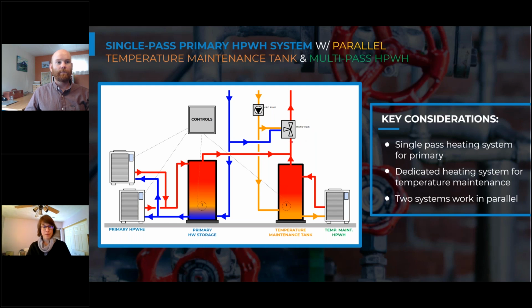Yeah, so this is a common way to pipe a mixing valve regardless of whether it's a heat pump or a gas water heating system, where we take the return water from our circulation, put it to the cold side, also take our city water connection and put it to the cold side. Those are typically connected together right before the mixing valve so that there's only 3 connections on this mixing valve, and these 2 are teed together right before that cool water connection. And this is an off-the-shelf component? It is an off-the-shelf component.